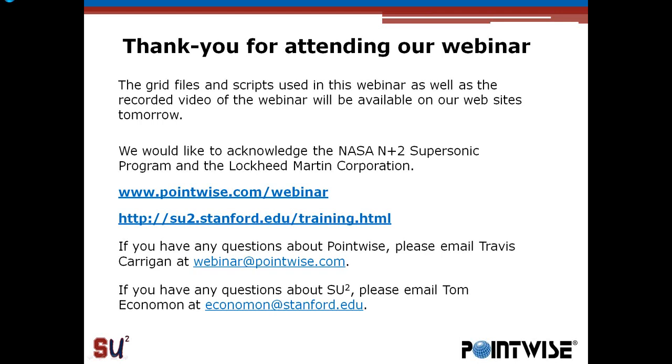Yeah, I'll just reiterate what you're saying. So it depends what you're doing. If you're really interested in low boom or boom predictions, low boom design, it will be very important that your cone, your outer region, is aligned with your Mach angle. But that's if you're really interested in boom.